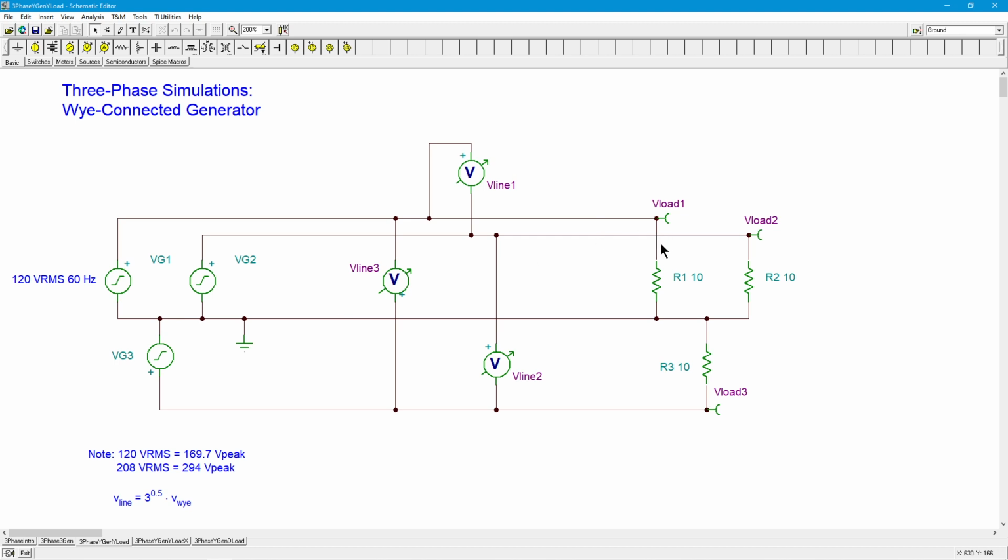All right. Typically, though, for things like this, you would probably want to use voltmeters rather than Tina's voltage point probe sort of thing that they have here. But either way, in this particular case, it's going to work fine. In some future examples, I'll just be using voltmeters right across these elements. But either way will work, right? So depending on the simulator, you probably have either something like this or a virtual voltmeter that you can stick out there so it's floating. It doesn't have to go back to ground. All right, so here we go.